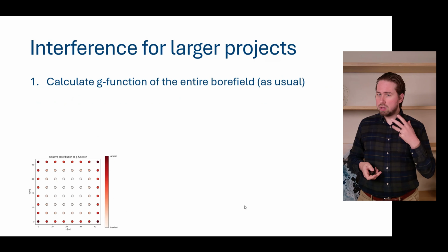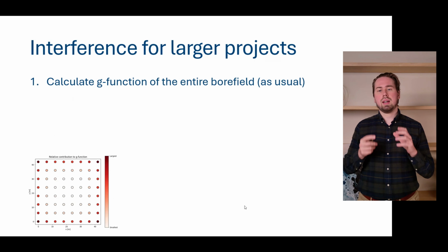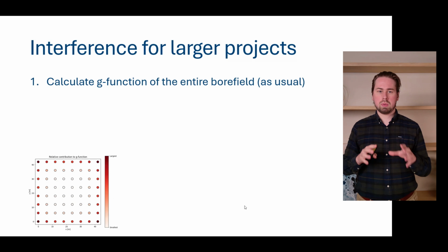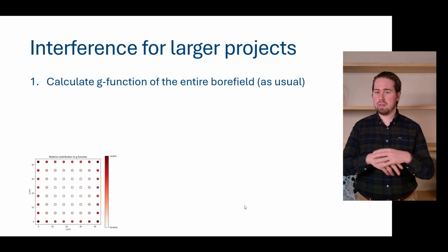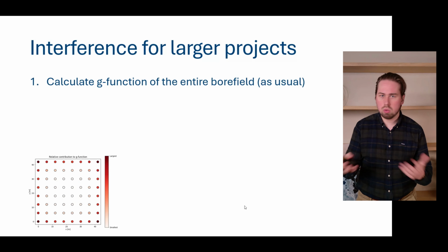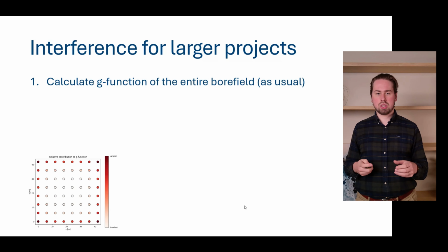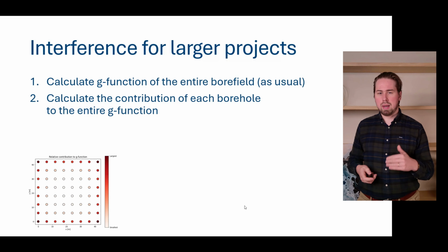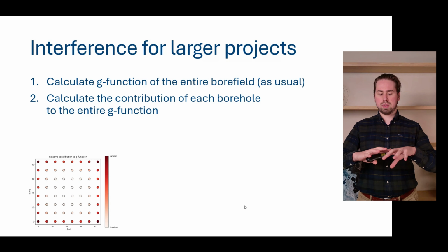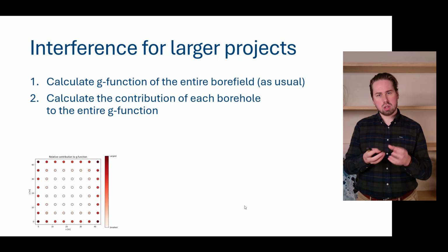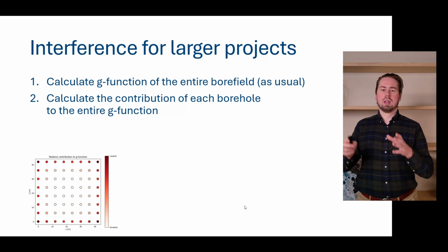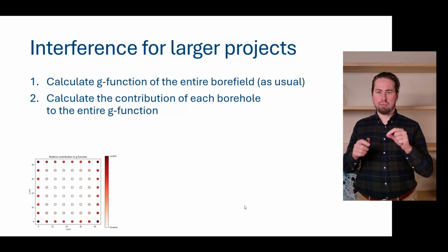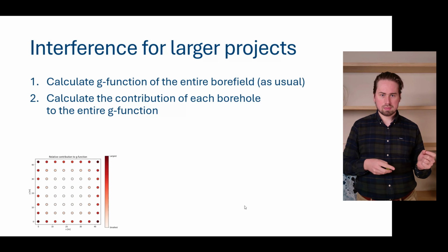So what we did is we developed a new method and we said, okay, let's start with the calculation of the G function of the entire bore field, like we always do for all geothermal simulations. But then instead of stopping there, we take a step back and we see, okay, now we have this holistic approach of the thermal behavior of our system. Let's see what the contribution of each borehole was.